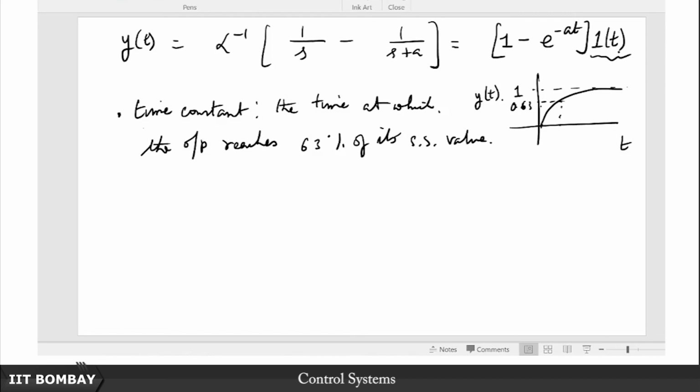So then instead of 0.63 you would have been looking at k times 0.63, and that would have told you your time constant. So this time constant is denoted by, let us say, this symbol tau. So this is the time constant. Now it might seem like, why bring in this 63% after all? It looks like a very odd percentage, like something divinely ordained. What is the motivation behind just choosing this figure of 63%?